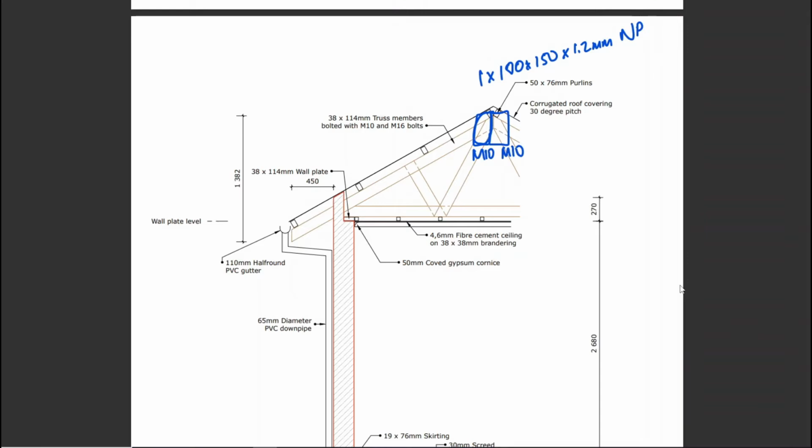I thought that's interesting. You've kind of taken two components, you've bolted them, and now you've brought those bolted pieces together. And now how would you fix this? You're going to have to nail plate it. And that was a scenario I don't think I've seen before. So I thought I better share this. You're going to put a nail plate across there, and you're going to have your bolts 1, 2. All right, that should make sense to you, because now you got, as a top view, timber, another piece of timber. Okay, and since it's sloped, you don't really see as much of it. Let's just draw that like that.